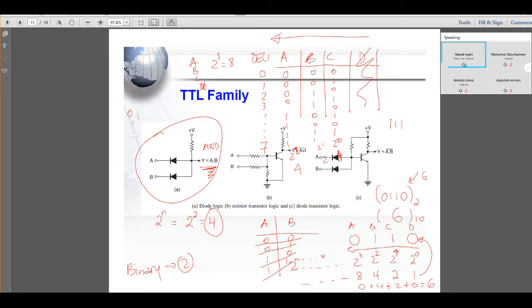0 means ground. You can make a ground. You can connect our input here to ground. If it's 1 logic, it should be 5 volts DC, which is VCC. So the first combination 0, 0 will be this one connected to the ground through wire, this one to the ground, and here we'll be having, for example, an LED connected to ground also, this side.